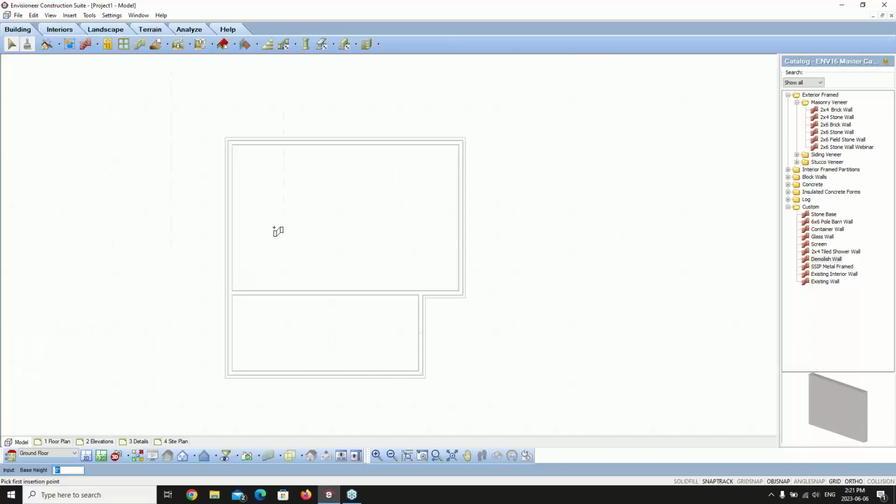So you can define exactly where you want the walls to go based on the intersection that you're going to be working with. If you also notice where my mouse is, I'm not even anywhere near that 10-foot mark. I just simply left click once and it automatically snaps that wall to that 10-foot point, and it then adds it in. Now we're going to see that new wall added in, and we're going to see that green dash dot line style for that wall.